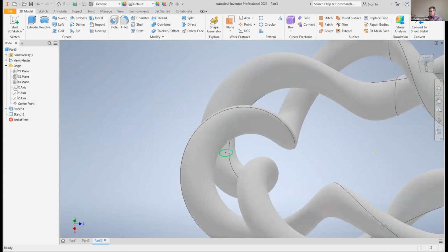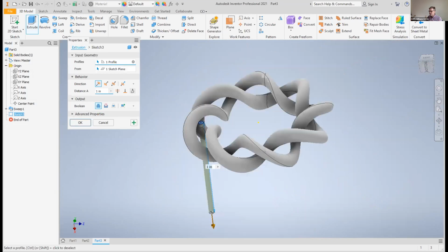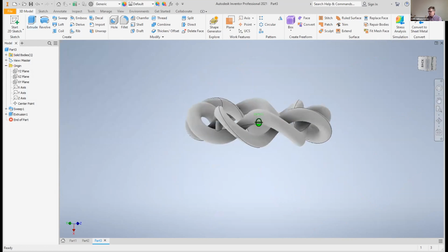So what I need to do now is extrude that. So let's extrude it. Yeah, that was a bad extrusion. I'm going to do a symmetric extrusion, so it extrudes in both directions like that. And we don't need an inch-long post. That's a bit much. I think we need 0.1 inches or something like that, right? And now I have constructed a support beam.